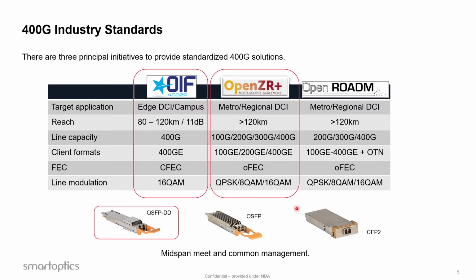On the CFP2 side, that is very associated with the Open ROADM part, where you also add the OTN framing, and typically you add a micro EDFA, so you get a higher TX power level from this. This means that this combination is typically used together with transponders and muxponders. And since I was going to focus on the embedded approach, I will not discuss that any further.